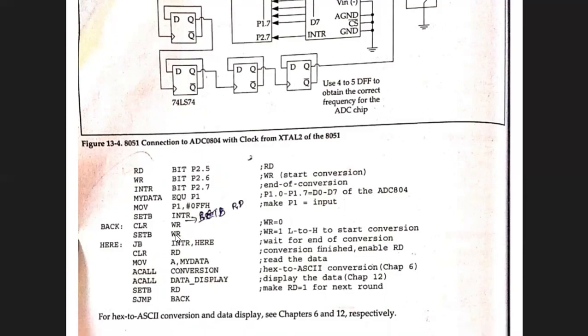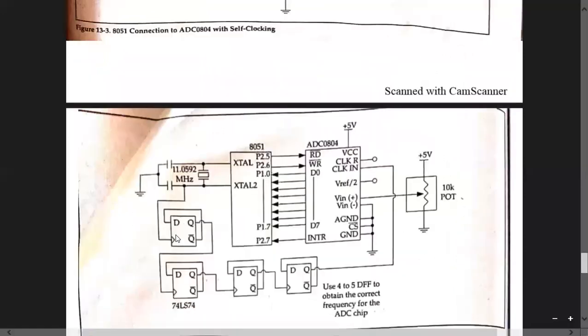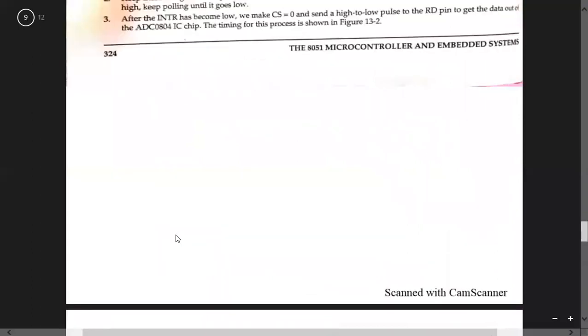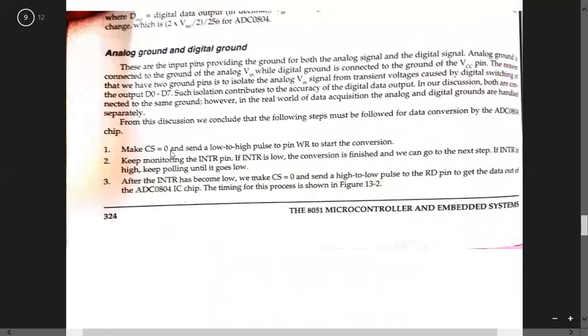Okay, we have the first step, that is setting CS equal to 0, clock source equal to 0. Yes, ma'am. Setting the clock source to 0 will happen internally, because that is a clock source. There is no need for the programmer to do it here.